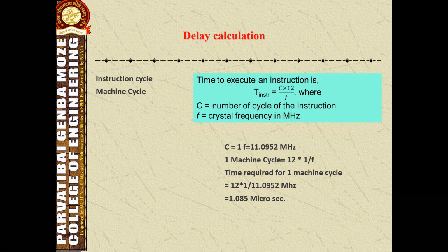So the machine cycle is nothing but the time required to accomplish any simple or complex instruction. If there is a program with a particular instruction or a complex instruction like a subroutine, such as the time delay we saw last time, calculating the time for its execution is called a machine cycle. A machine cycle may be an opcode fetch, a memory read or a memory write. All operation times can be calculated using the machine cycle.